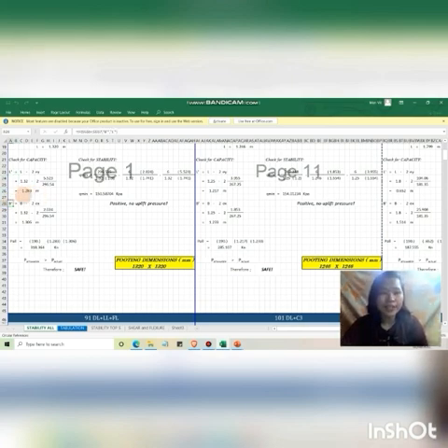For our effective length, we will use this formula: L prime is equal to L minus 2EY. Our EY is equivalent to MZ over the P total, with MZ here 5.523 and the P total 296.54. Substituting the values, we arrive at the answer of 1.283 meters for our effective length.